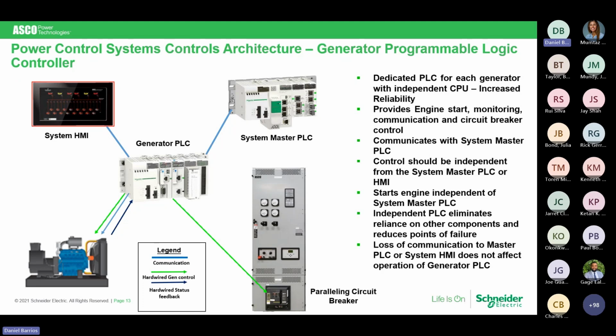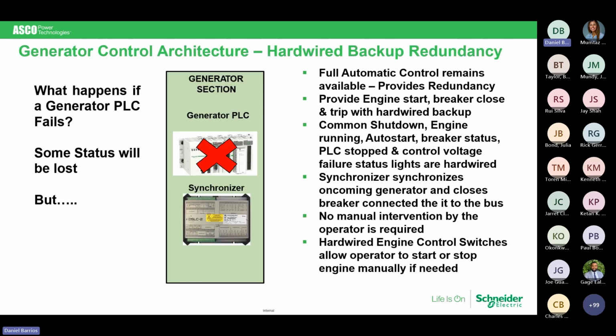However, since I've lost my load control portion by losing my master control, I will be able to transfer my priority 1 loads. However, no signal can be sent to the priority 2, 3, and so on, releasing that hold and letting them transfer to the emergency side. We can discuss that further with you if you have a specific application.